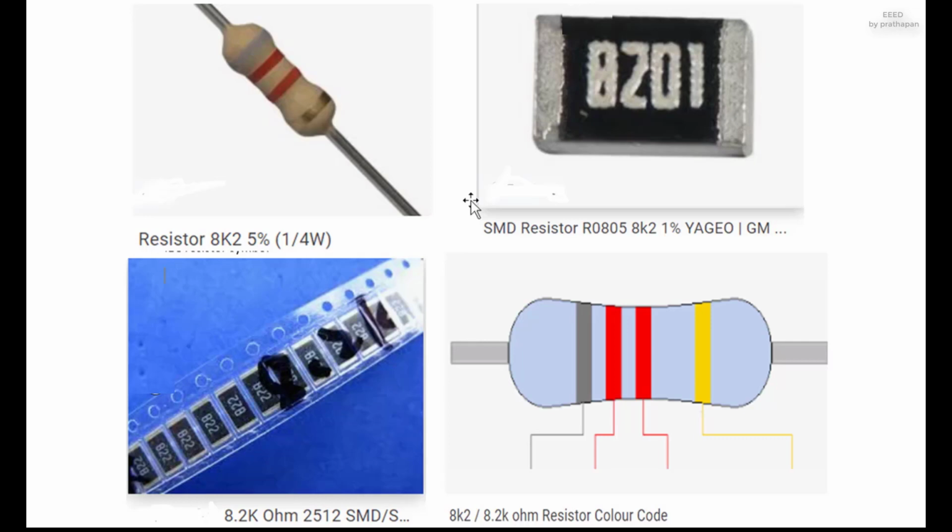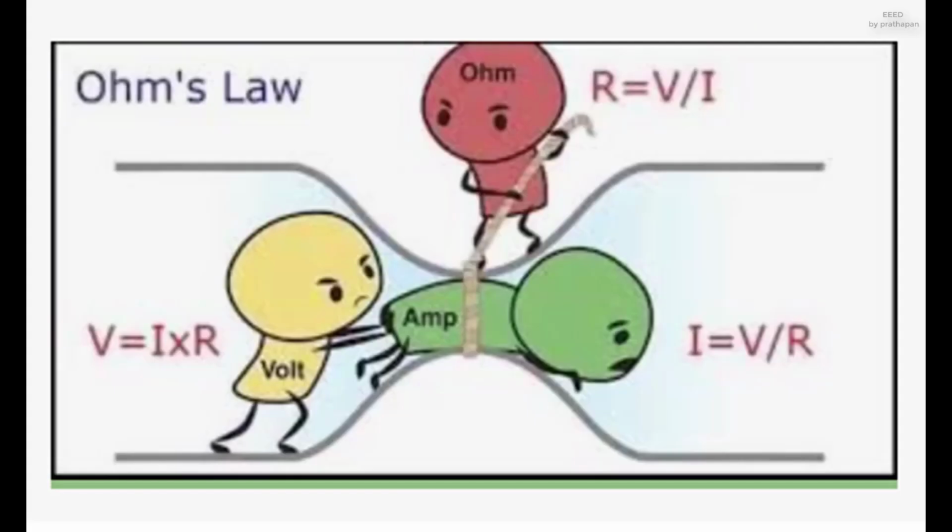Additional zeros imply a tighter tolerance, for example 15M0 for 3 significant digits. When the value can be expressed without the need for a prefix, that is, multiplicator 1, an R is used instead of the decimal separator. For example, 1R2 indicates 1.2 Ω, and 18R indicates 18 Ω. Theory of operation. Ohm's law. The behavior of an ideal resistor is dictated by the relationship specified by Ohm's law.